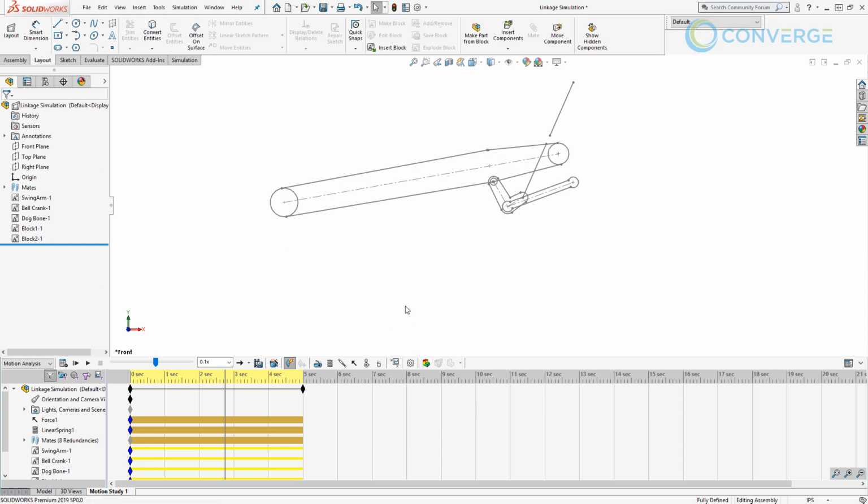But keep in mind that if you take this design into 3D and you come back in and you continue on with your motion analysis, we can pick points in time to analyze the stress and the reaction forces based on the parameters that we've set up. If you set up a simulation in SOLIDWORKS and you talk about the contacts and the loads and constraints, that's all taken care of by you simply setting up a motion study and applying mates inside of the assembly.